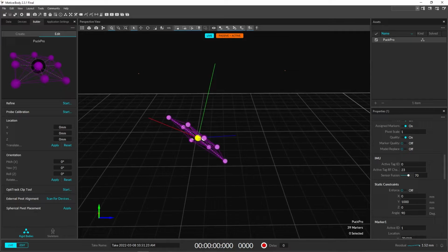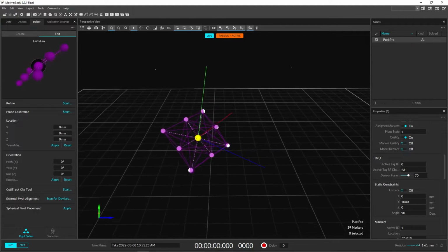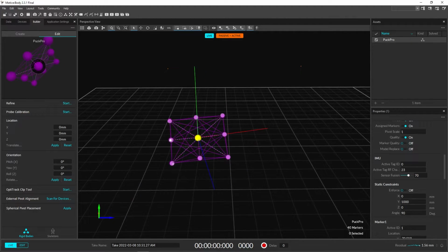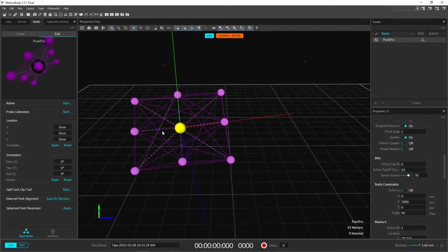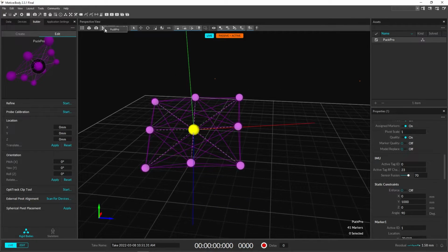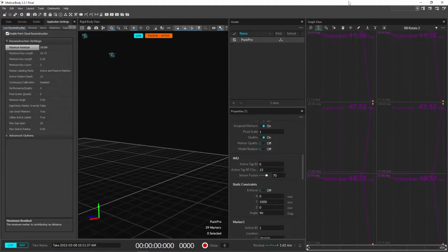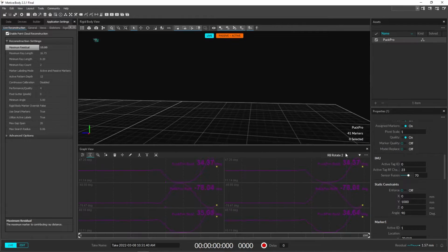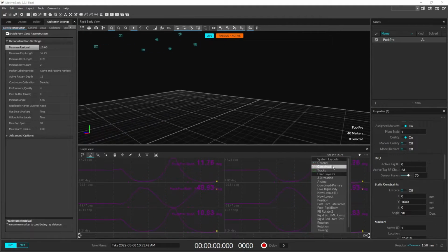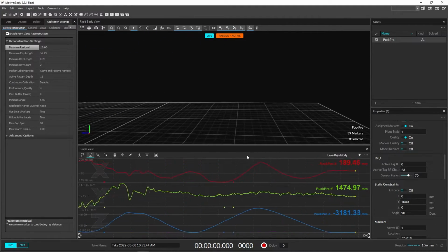At this point, you are tracking with both the optical marker data and the IMU data through a process called sensor fusion. This takes the best aspects of both the optical motion capture data and the IMU data to make a tracking solution better than both. Optionally, you may now turn down the minimum markers for your rigid body down to 1 or even 0 for difficult tracking situations.